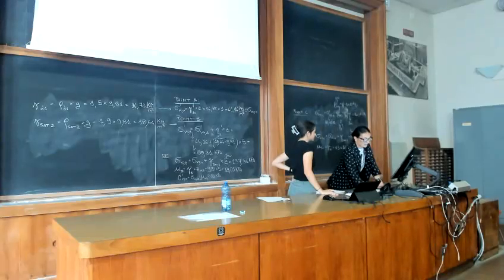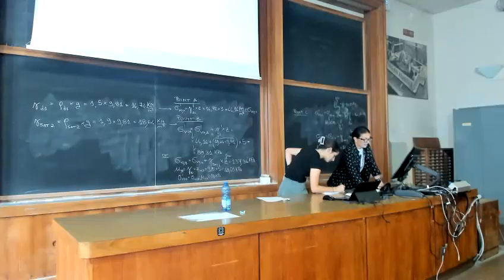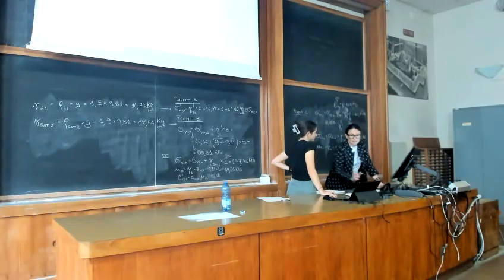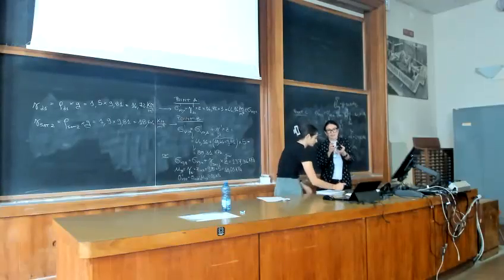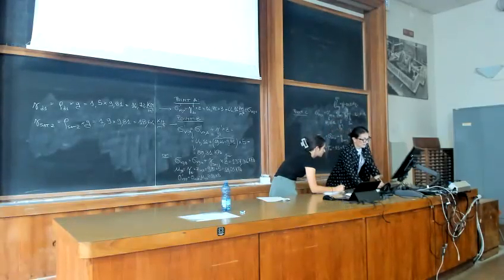So in order to find out the stress state of a soil element below the water table, you have to consider total stresses, which include the saturated unit weight. Saturated unit weight is the one of grains plus water, minus pore pressure, the pressure of the water, which is provided by gamma W in hydrostatic conditions.